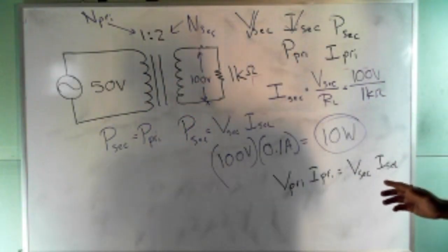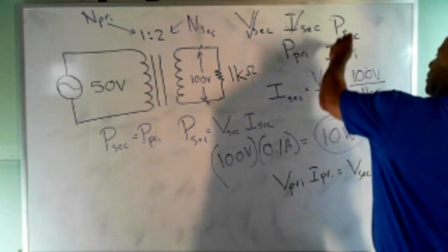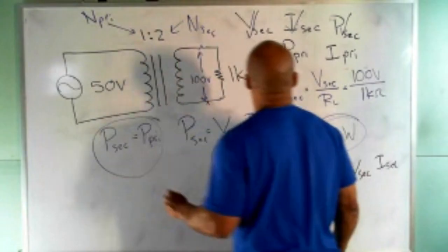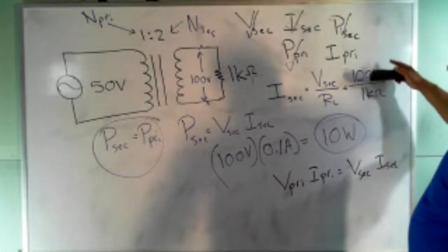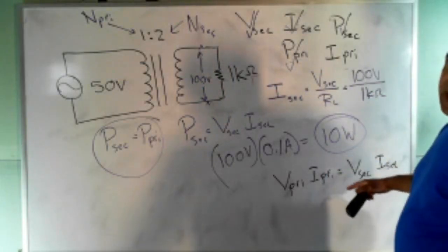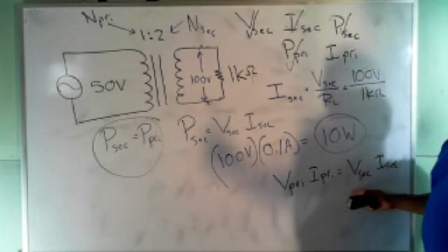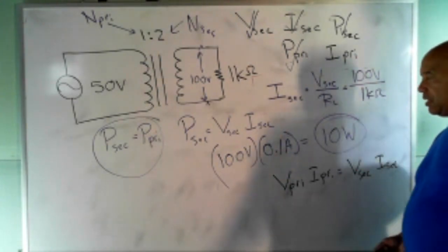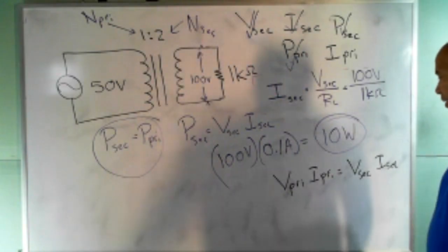And now if we have another load that's not resistive, then we've got another problem, but we're going to keep it simple. So we found PSAT, and since we're assuming efficiency of 100%, we've also found P prime. Well, these will always be equal. Now to find I prime, you could use that equation that I used, but I always use this power equation, and I'll show you why. I prefer to use this than the one I just erased. So we just solve this for I prime.